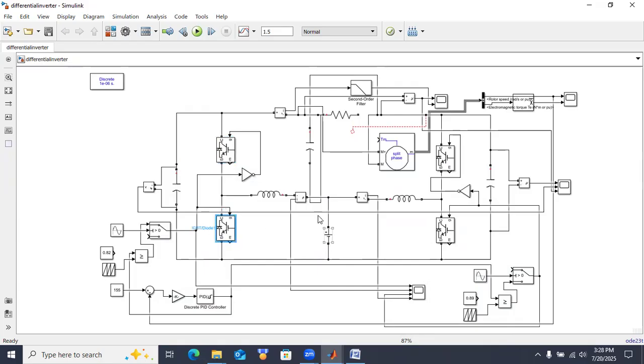So at the time, this inductor and this voltage source will get added. So the output voltage will be input voltage plus inductor voltage. Similarly for this capacitor, same thing. Input voltage plus inductor voltage is equal to this capacitor voltage. The difference in these two voltages are combined across the load so that we will get differential output voltage.